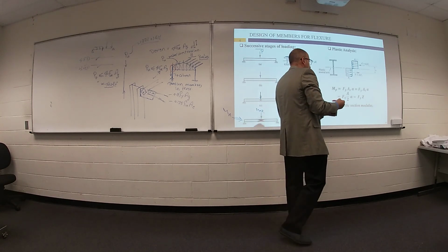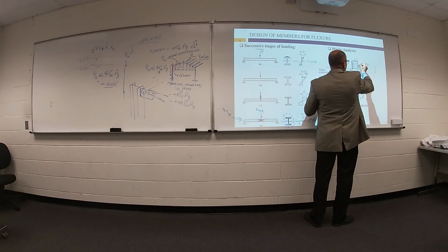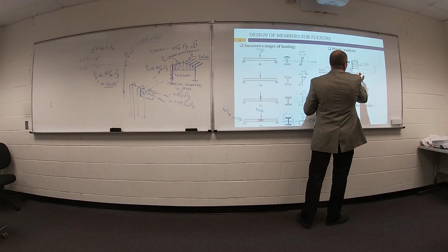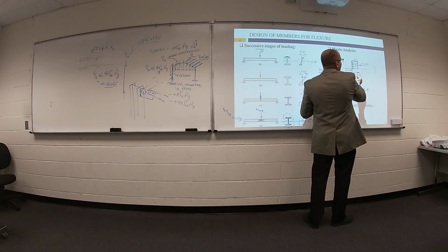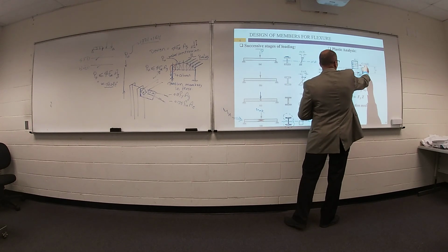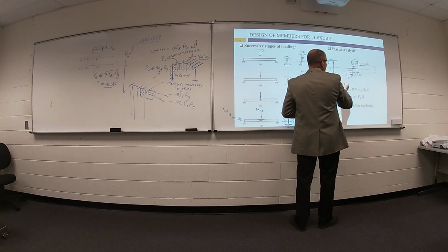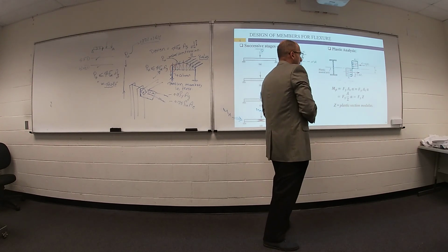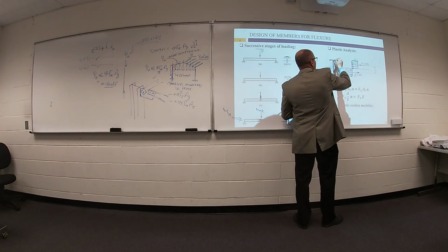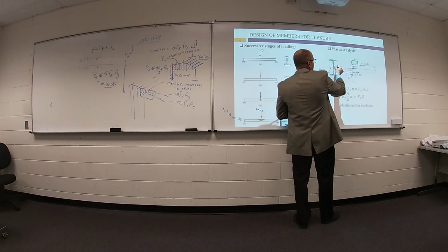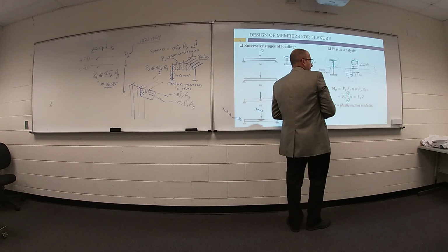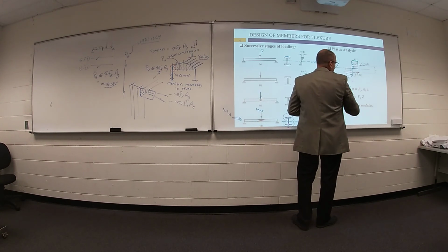If you get the equivalent force for this stress block, which is called C, and the equivalent force for this block, which is called T, and your cross section is in equilibrium, so this compressive force equals this tensile force. C equals T. C is your F yield times this area, A divided by 2, which is called area under compression.